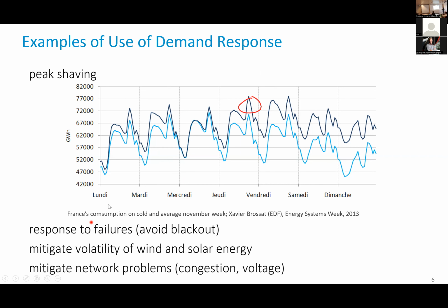That's, I would say, peak shaving. And if we don't do peak shaving, if there is a problem here, what will be the result? If we don't have enough capacity, that would be load shedding. If the operator of the transport network, Swissgrid, for example, sees that there will be a shortage, then they will declare that we cut power availability, but that will be planned and managed.